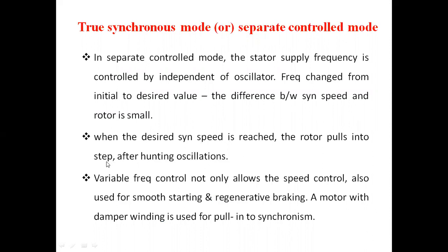While operating under separate controlled mode, the number of hunting oscillations is higher. So to eliminate the hunting oscillations, we are using the damper winding. At the same time, variable frequency control not only allows speed control, it also provides smooth starting and regenerative braking.